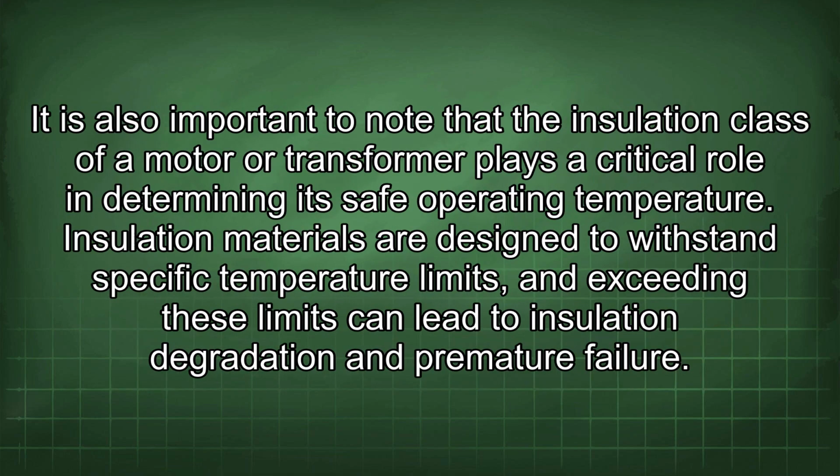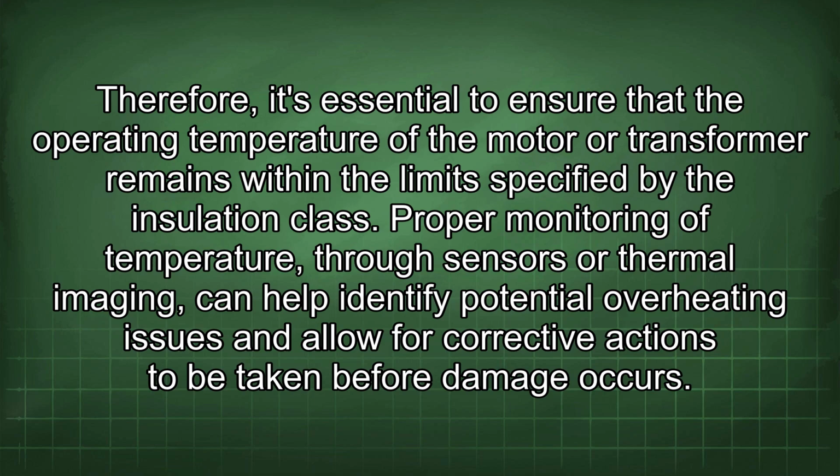It is also important to note that the insulation class of a motor or transformer plays a critical role in determining its safe operating temperature. Insulation materials are designed to withstand specific temperature limits, and exceeding these limits can lead to insulation degradation and premature failure. Therefore, it's essential to ensure that the operating temperature of the motor or transformer remains within the limits specified by the insulation class. Proper monitoring of temperature through sensors or thermal imaging can help identify potential overheating issues and allow for corrective actions to be taken before damage occurs.